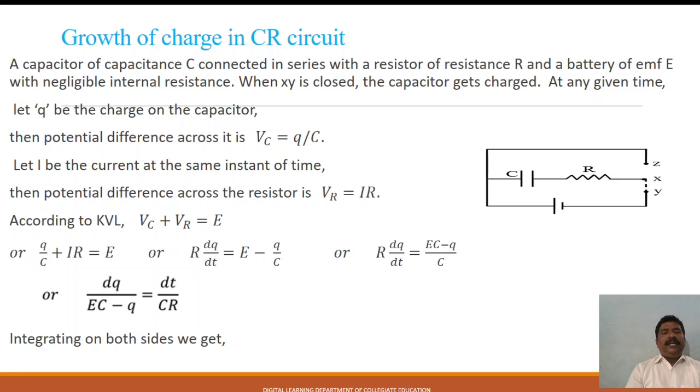In the inductive circuit, the current is I equal to I naught times (1 minus e to the power of minus R by L into t), where tau is the time constant, equal to L by R. When t is equal to tau, L by R, it shows that 63.2% of the maximum value can be stored in an inductor.